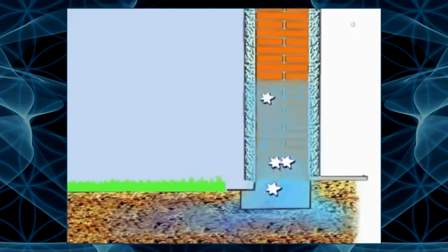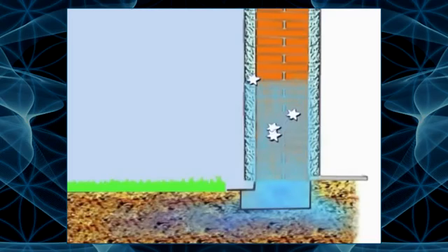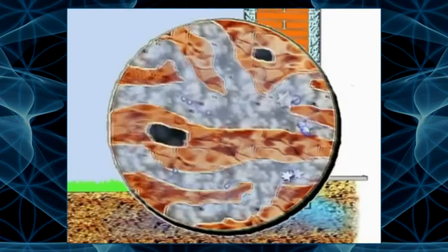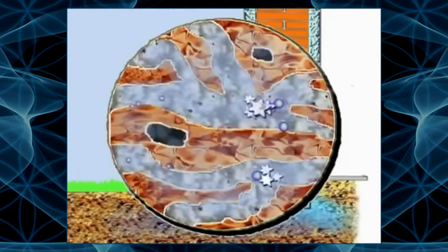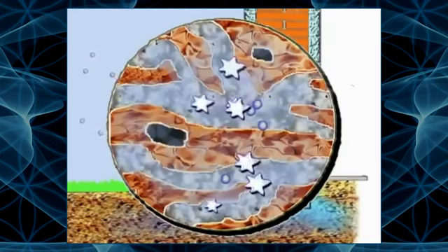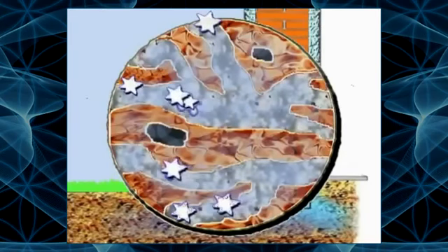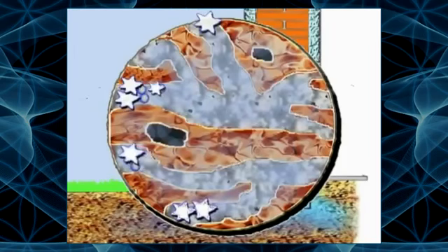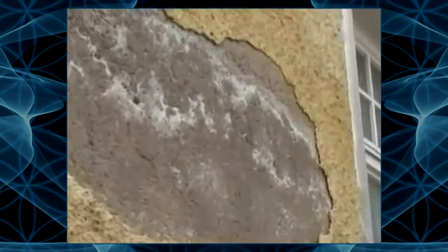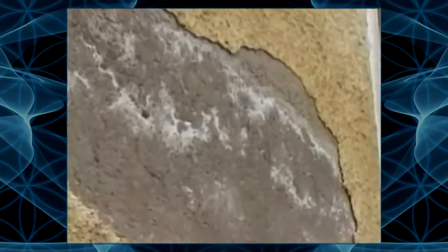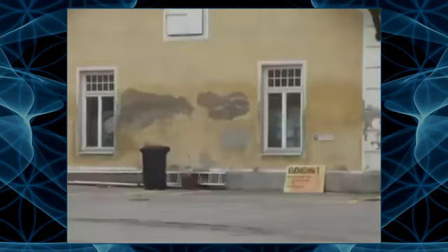As a result, salts that damage the basic structure of a building enter the masonry from the ground. The salts rise dissolved in water into the capillaries of masonry and are deposited in the evaporation zone in higher layers of masonry, especially in the pores of the plaster. The salts of building materials are also dissolved by the moisture stream, rise and additionally enter the pores of the plaster. Due to such evaporation, most salts are deposited in air pores, which are crucial for the regulation of the atmosphere in the room, and clog the pores. The breathability of the plaster is thus reduced.